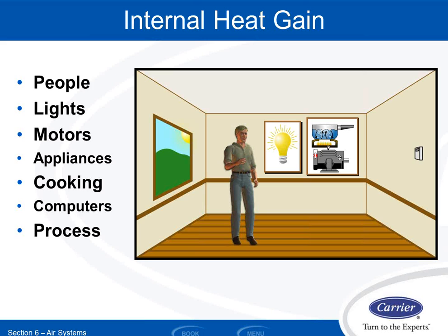The lighting also could be a fairly large source of heat energy. More modern LED bulbs give off very little heat, but older technology that you find in lots of buildings and lots of houses with incandescent bulbs and stuff like that give off a ton of waste heat, and we need to take that into account when we're removing the heat. And similarly, if I know the building is going to be designed with LEDs or redesigned with LEDs, I need to take that into account because the size of the system I thought I needed is going to be smaller for the cooling system than I originally planned.